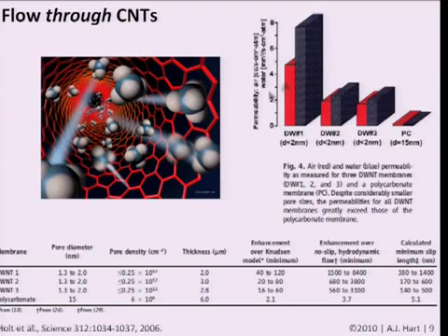And the results here show the relative permeability of air and water in these units; you can just say this is sort of flow rate at a certain pressure condition. For 3 membranes they made, DW just means double-walled, because their nanotubes had 2 walls, relative to a control sample, which is a polycarbonate membrane that is typically used for filtration.